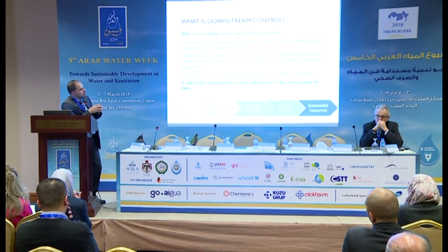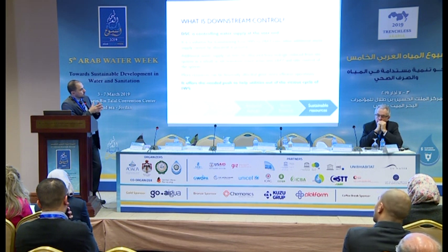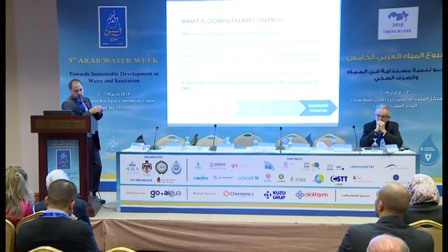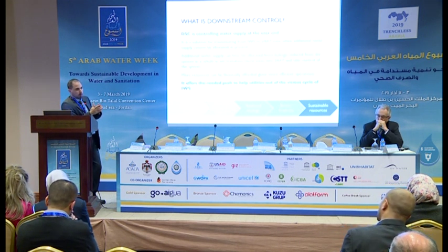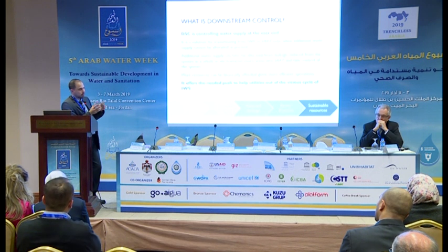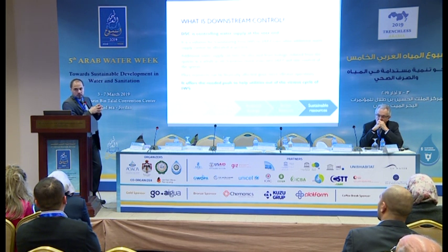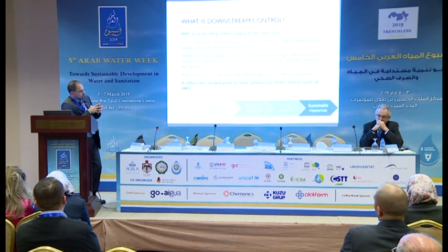Of course, later on, we try to reduce the pressure through pressure reducing valves. And in these situations, we will stimulate the 24-hour with less pressure in the system and delivering the water on the rational supply. And the benefit of that will be explained later by Pampus. So with having this, we can apply all the non-revenue measures on the network through even leak detections, better isolations, if there are problems, illegals, and etc.